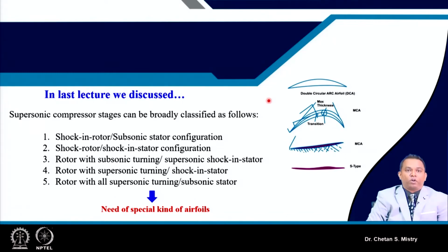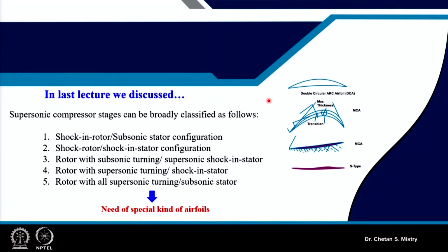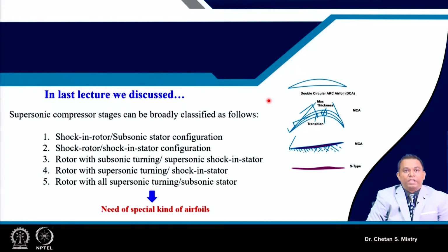Now, to understand this part, we are looking for special kinds of aerofoils. If we have a rounded leading edge, it acts like a blunt surface, and when the shock strikes it, it will not give an attached shock, but may give a bow shock. So under this condition, a rounded leading edge with thickness will not be applicable.